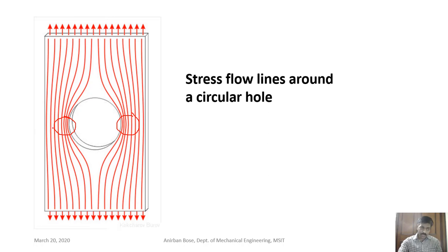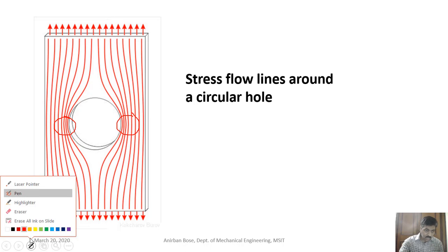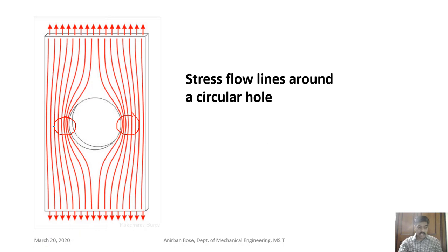If you want to see how, because of the stress concentration, the stress is distributed, if you draw a line along this section, the stress field will vary like this. That means as you go away from the hole, the stress is small, and very close to the hole, the stress is very high.